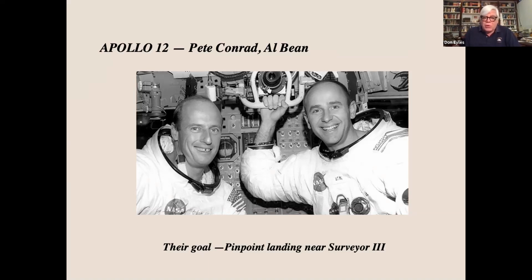And as I said, Apollo 11 was about 4 miles off. How did we fix that? Well, it turned out that ground tracking, when the LEM came around the side of the moon for the last time before making the landing, was a good setup for ground tracking to pin down the velocity of the LEM and its exact position. And this was the one case where help from the ground was necessary. We could not make an accurate pinpoint landing without help from the ground. I know that what's being looked at now for lunar landings is a pattern recognition system that'll recognize the pattern of craters automatically. But of course, we did not have that.